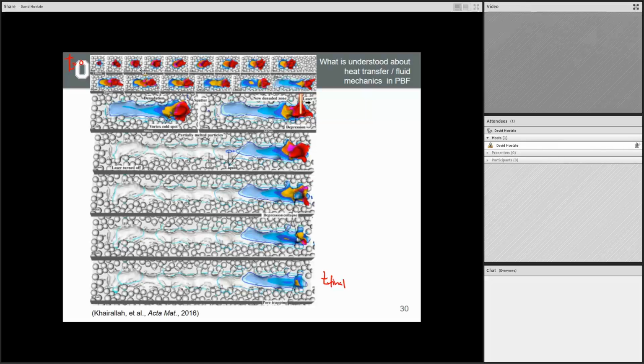hole driven into the material. We saw this with the X-rays as well. We saw basically this driving of a pore into this surface. In general, this pore gets more molten metal flown inside it, and so it collapses and doesn't cause a frozen pore to be permanently stuck in there. But you see there's this kind of divot or depression underneath the laser. So it goes along. You see in its wake, it leaves material that's getting colder but still molten, and then eventually, especially here, you can see it starting to freeze, right? This is the point where some of the material that was at one time molten now becomes solid